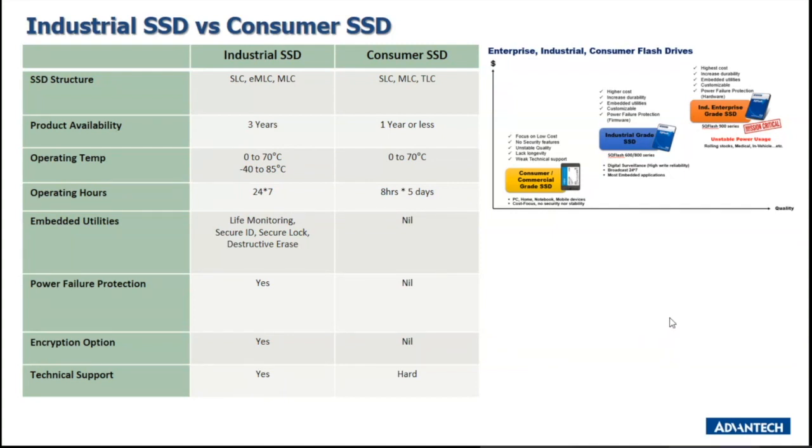Moreover, data integrity is also very crucial for embedded applications. During unexpected power failure situations, data writing may not be able to complete, and it will create read-write errors, especially in mission critical environments, for instance, the aerospace industry or in-vehicle applications.